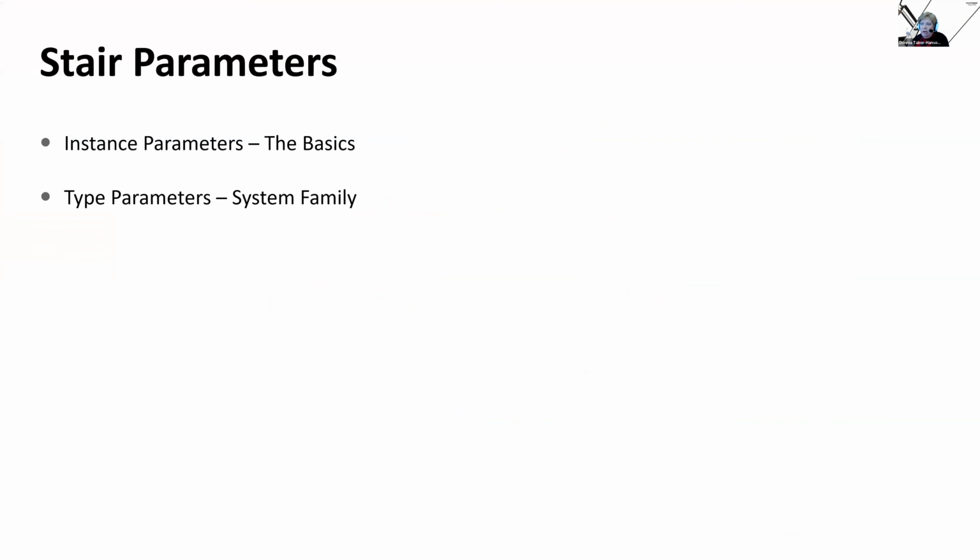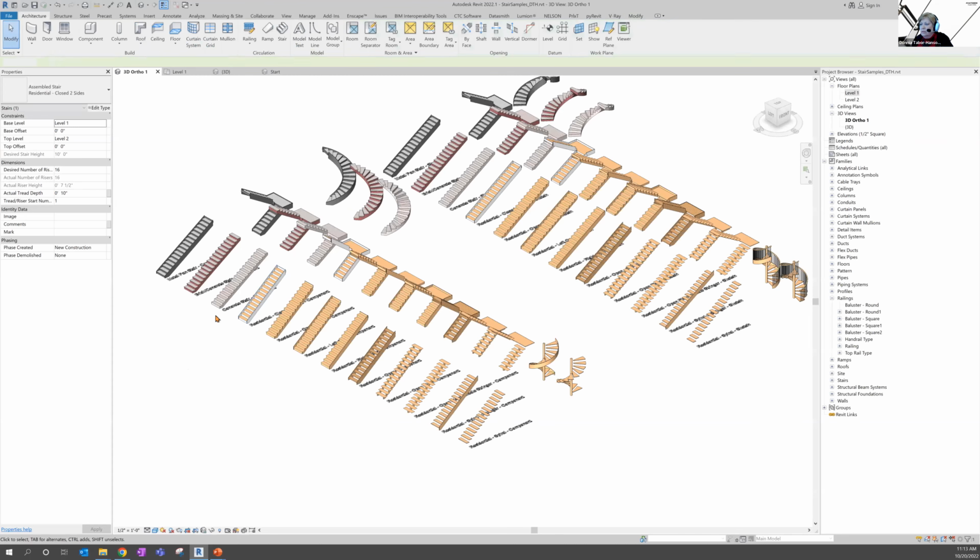So we're going to look into a little bit more detail. You know me, I go into the weeds. But we're going to start with looking at the calculations. These are only done in creation only. You can't go back and take a family and redo its calculation once you've put the family in. Just rip it out and start again. It's just quicker than trying to beat your head on this. So it's only when you're doing creation that you're going to see the calculation values that you can change.